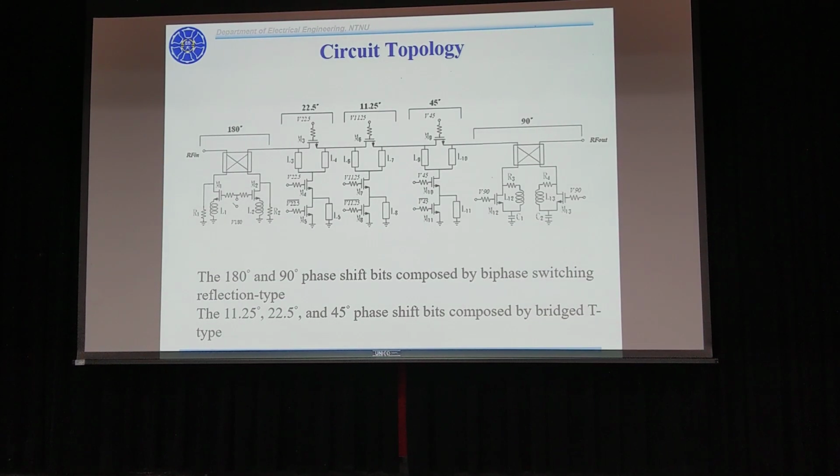The switching type phase shifter has a digital control mechanism, and it can change the reflection load by selecting the voltage to let the 5 bits have the phase shift state and the reference state, in order to have a compact chip area and minimize the influence caused by process variation. Some of the inductors of the phase shifter are placed as microstrip lines on the CMOS process.